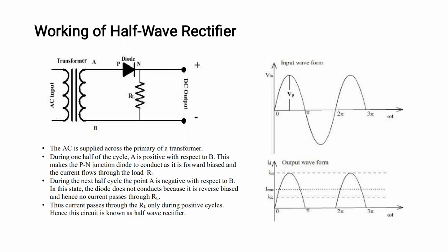The diode is in series with the transformer secondary as well as the load resistance RL, and the transformer primary is connected to the AC input. After each and every half cycle, the AC voltage across the secondary winding reverses its polarity, and the diode is forward biased and conducts current during the positive half cycle of the input AC voltage.